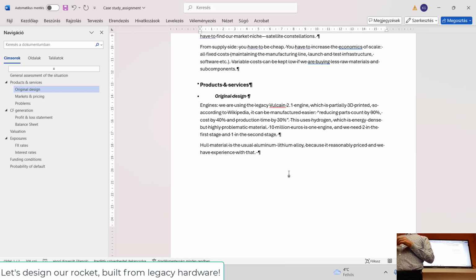Do you remember the Titanic disaster? I mean the submarine Titanic disaster from last year, when the wealthy people built their own submersible and then it imploded in the deep sea, close to the original Titanic ship. In this case, they were building this carbon fiber tube for themselves. They put two titanium half cylinders front and back, and what happened is that it collapsed in the middle. Practically it shot out the titanium ends and all the windows immediately.